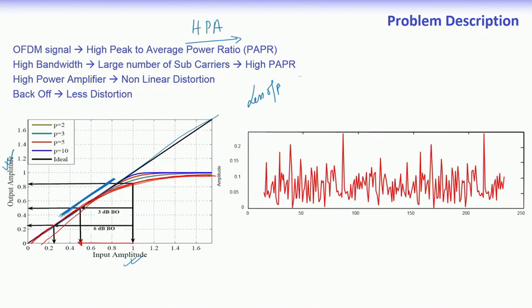Less output power would mean that the operation has to be sustained for a longer duration of time in order to send the same number of bits, plus there is power efficiency loss. So, this effectively leads to a greater loss of battery power, especially in handheld devices. For OFDM, PAPR causes a lot of restriction in having a large coverage area, so we need to have several mechanisms to take care of this.